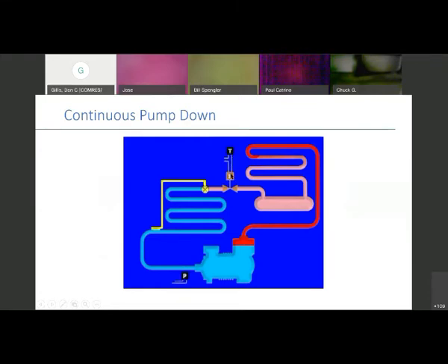It activates, sends power to the head here, and opens our solenoid up. Refrigerant goes through our TXV, comes around through the evaporator, past our bulb, past our P, which is the low pressure cutout, through the compressor, back through the dark red here, and into the lighter red.